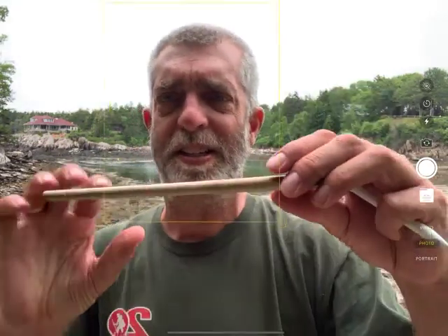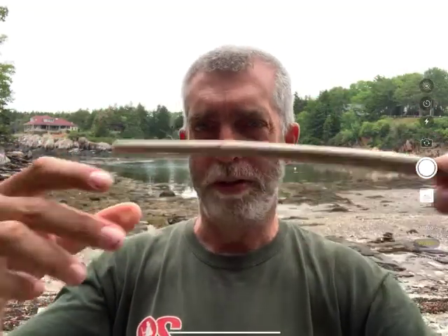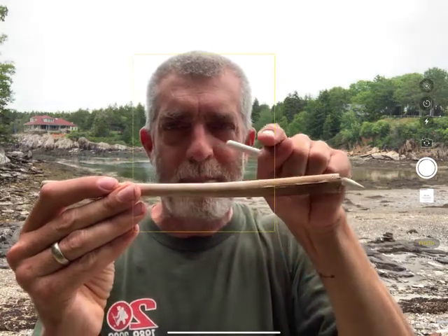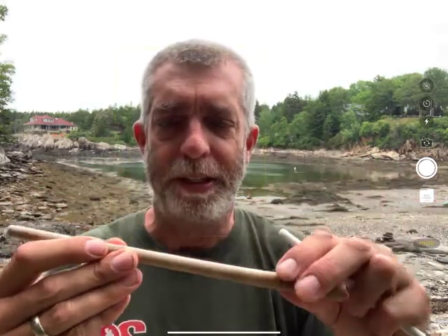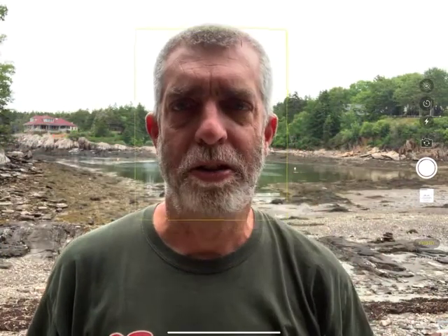So let's say I'm bending this thing. And so I run down to the machine shop and run this through the lathe, and I don't do a very good job. I kind of stop to talk to a friend and then keep cranking the thing, whatever. I've got just a bunch of little bumps, right? I'm not going to have an awesome surface finish on this thing. And every one of those little bumps is a potential stress concentration. Tiny, almost immeasurable stress concentration, but it's there for sure.